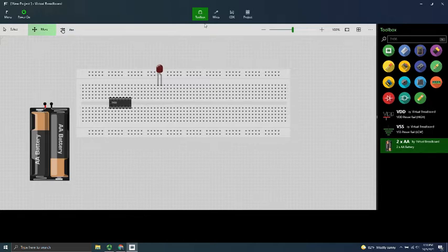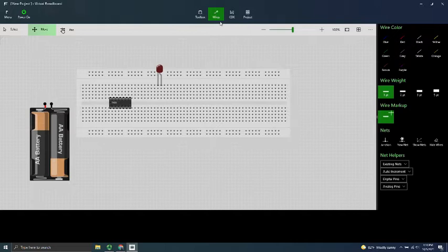But let's go ahead and start connecting things. If you look up here to the very top, we have wires. So we can start connecting some wires. I'm going to start connecting my power, and I'm going to use the color code that we normally use for jumpers. So I got red. This is what the wire looks like, and the size of the wire is good enough for our simulation here. I'm going to start from there, snap it, and then click right here.